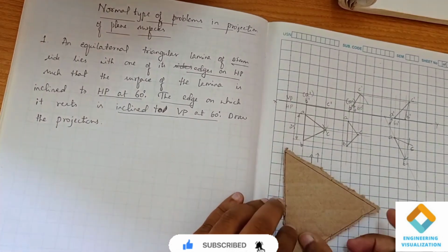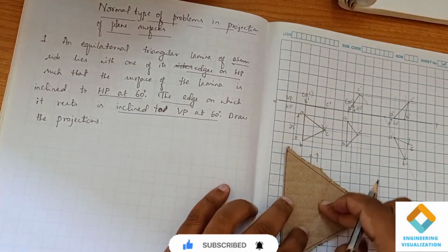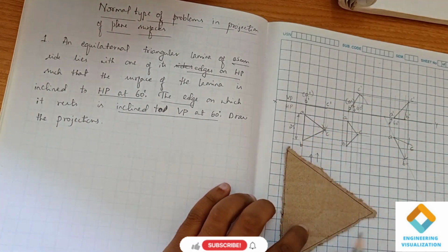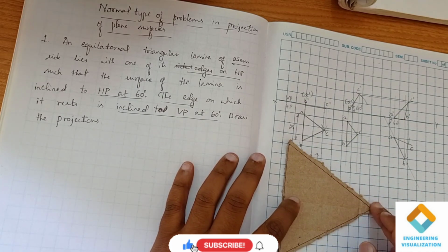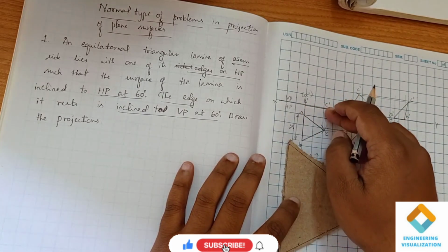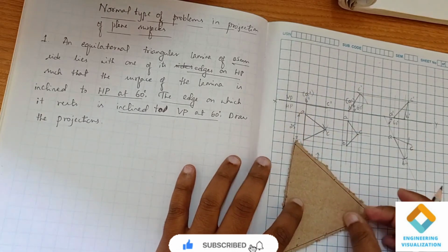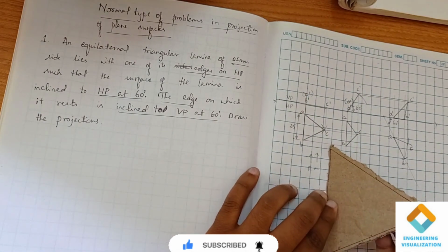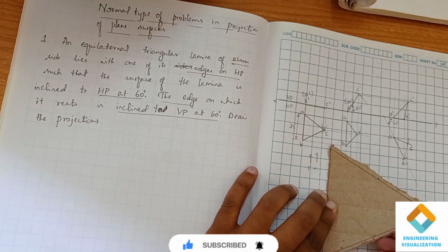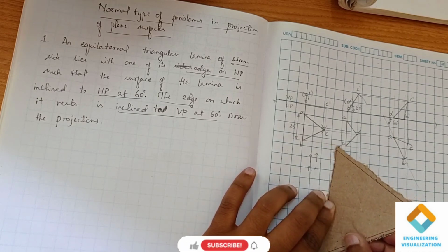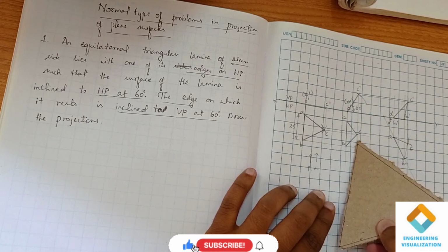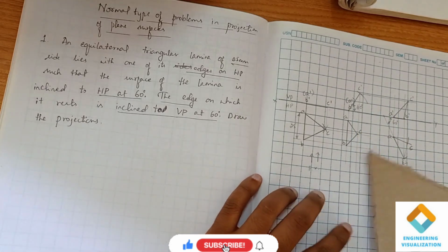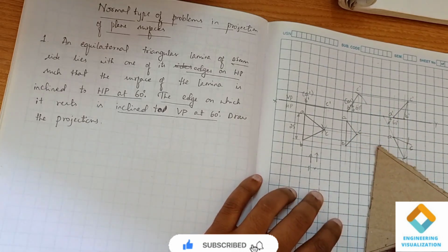So the problem proceeds: in the first position, we have drawn a top view and the front view. In the top view we get the same dimensions, and in the front view we are able to see only this B dash C dash, that's why B dash C dash is visible and A dash will be in brackets. Now in the second position we have inclined like this. That is, we incline the B dash C dash line in the front view by an angle of 60 degrees. Then after that we did this position. Now in the third position, we have to incline this lamina by an angle of 60 degrees.